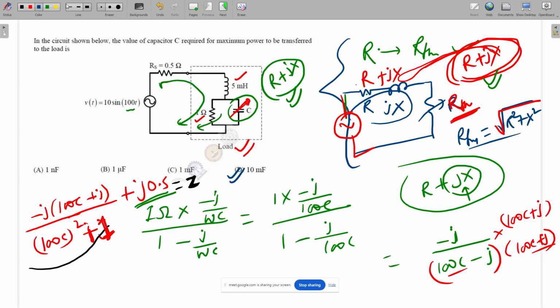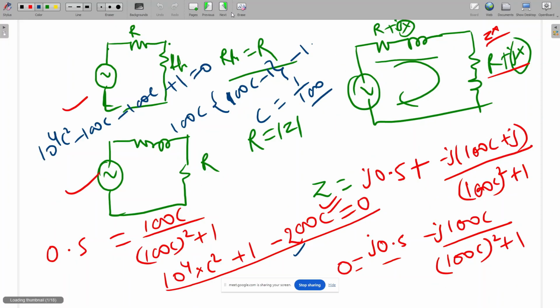10 millifarad. So these four concepts you should memorize. Whenever this type of question comes, either L or C can be given as variable. If any combination of network is there, L or C, we have to make the load purely resistive. Accordingly, we can calculate either the L or C value. Is it clear to all? Can I move to the next question?